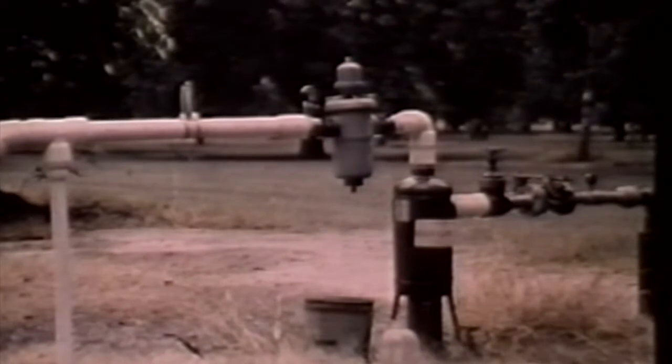The control head serves as a control station for the trickle irrigation system. The control head generally consists of the water measuring device, valves, injectors, automatic controllers, pressure regulators, and filters. In some installations, additional pressure regulators and filters are located at the entrance to the manifold or lateral lines.